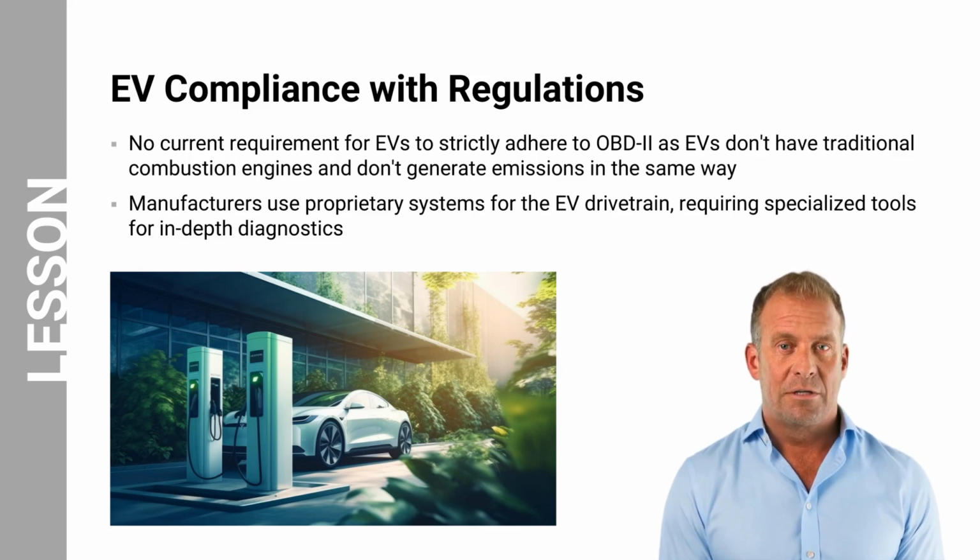Unlike gasoline vehicles, there's currently no legal requirement for EVs to comply with the full OBD2 standard. This means they may not have the standardized diagnostic port or necessarily use the same communication protocols. Many EVs, especially those with hybrid powertrains, do have OBD2 ports and can communicate using the OBD2 standard for certain data points. This allows technicians to use standard tools to diagnose some issues.